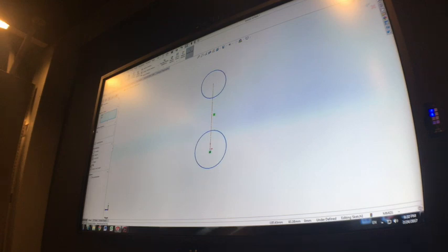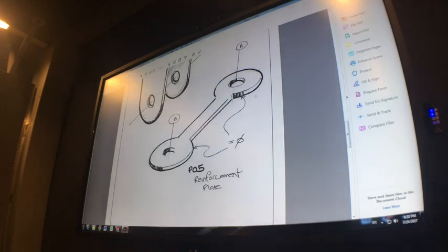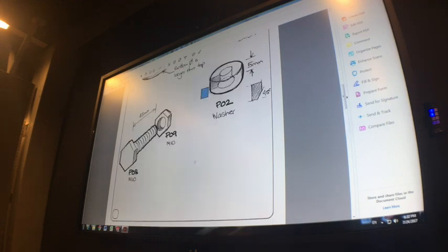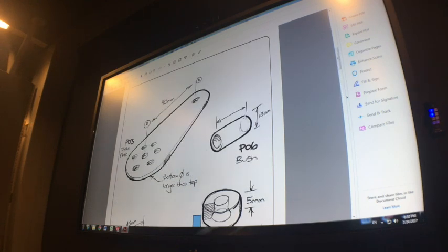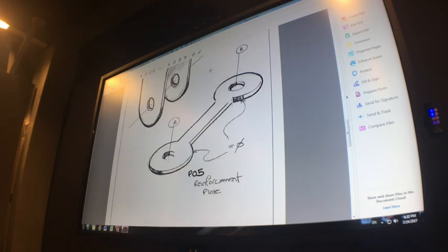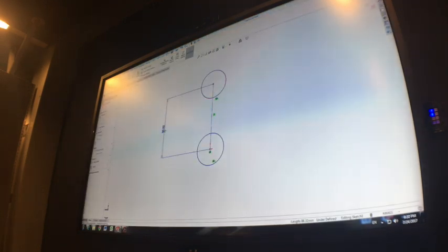Now, because they're the same size, we'll make them equal in diameter. And we've got that A to B dimension on this one. That matches here, A to B, which is 90. So we can put 90 in for this dimension as well. So what plane are you on? The right plane. Not a big deal if you're on something different, but I'm on the right plane.